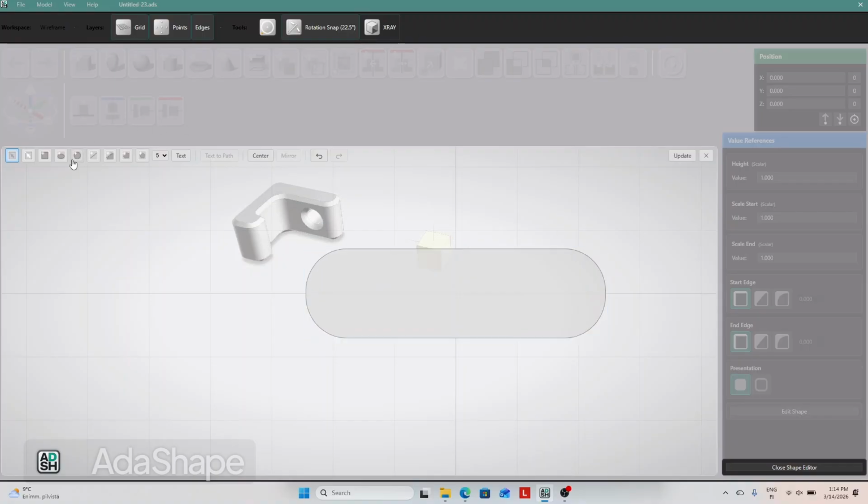We can use the Circle tool over here. The difference between a circle and an ellipse is that the circle is always guaranteed to be circular, which is very important if you want to make mechanisms. The ellipse is a more free-form tool. In this case, we want a circular hole. I'm going to place this circle over here, then press Ctrl-C to copy and Ctrl-Shift-V to paste in place. Now I'm going to click Mirror, so we get a nice symmetric pairing of these round holes. We can join them into a group or do a Boolean union operation.